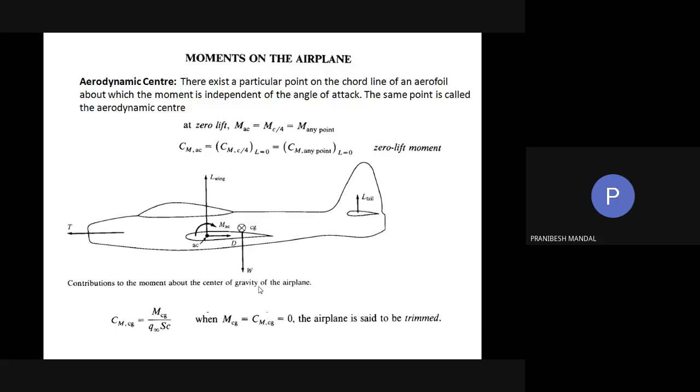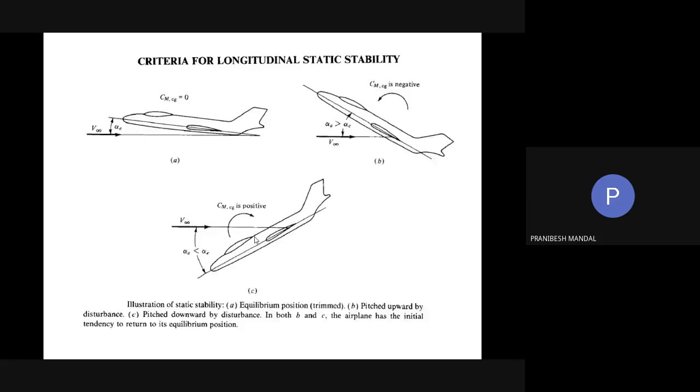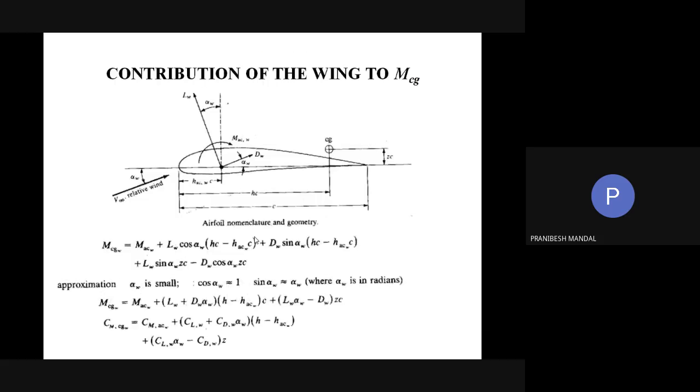So what they actually suggested is, instead of the model of the wing only, for having those three wind tunnel data, let us have a model of the wing body combination. That is a body connected to two wings, the tail is not there, obviously. So the model of a body with two connected wings is tested in the wind tunnel in order to get those three data: